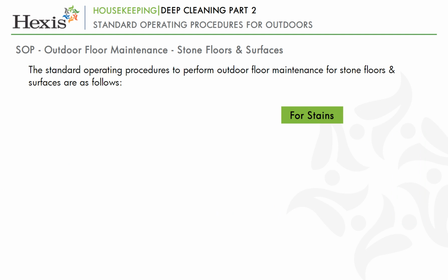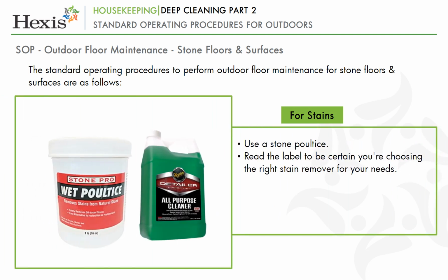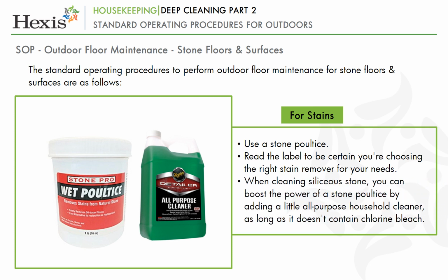For stains, use a stone poultice. Read the label to be certain you are choosing the right stain remover for your needs. When cleaning siliceous stone, you can boost the power of a stone poultice by adding a little all-purpose household cleaner, as long as it doesn't contain chlorine bleach.